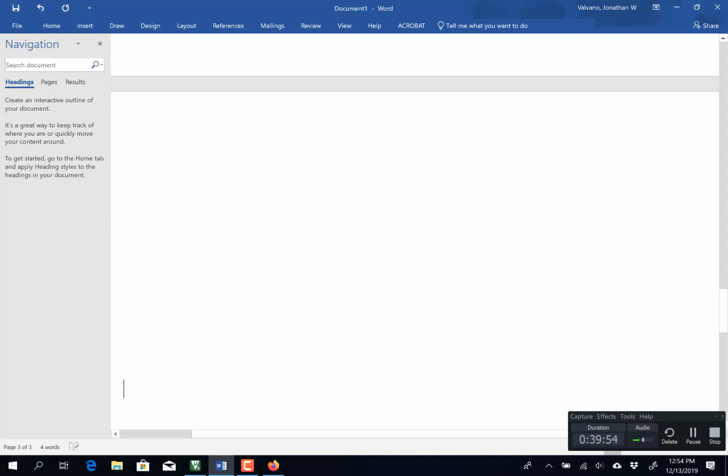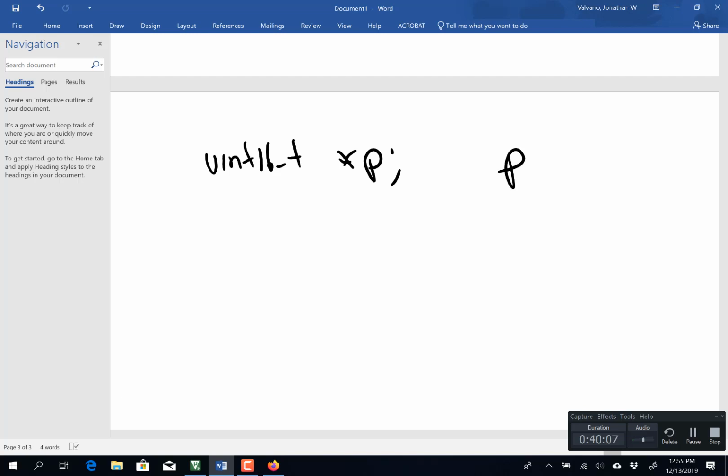So whenever you have a uint16_t, translate that to assembly language for me. You're allocating two? No, it's a pointer. No, it's always a 4. Regardless of what's on this side of the star, all pointers are 32-bit numbers. Okay? Let's do another one.